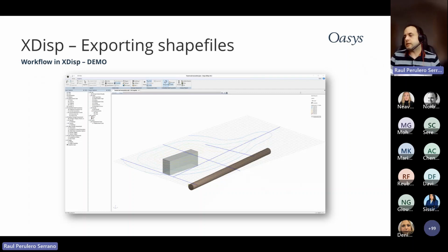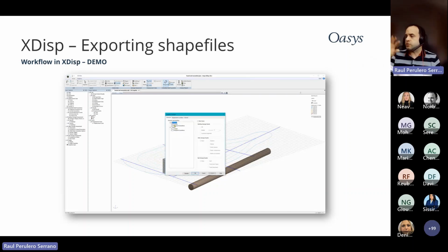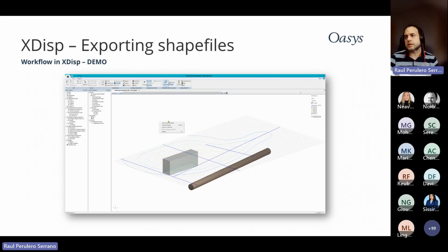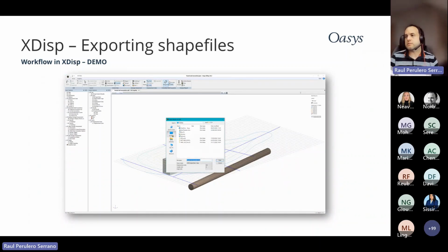So what you can see here is a GIF of how you will soon be able to do this. You just go through the settings wizard, and you can select the lines, the grids. In this case, it's the grids because you've got the information set in 2D. You can select the export magnitude that you're after, and then just a couple more clicks, you select the grid that you want. In this particular case, it has a single grid, and then you just save it on your computer. That's as simple as those 3 steps. And there we go.